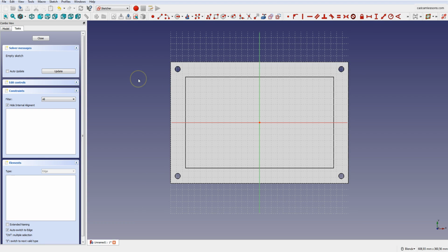Okay. We draw circles with a diameter of 15 mm, with the centers in the same place as the centers of the circles with a diameter of 9 mm. So the option create an edge linked to an external geometry will be useful, and this option allows us to convert the 4 previous circles as a reference geometry. Okay, and now we can use this point to draw other circles.